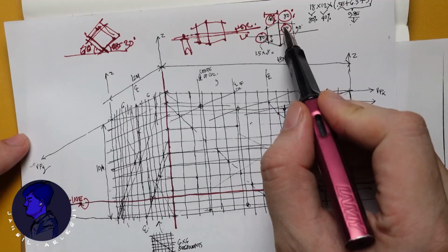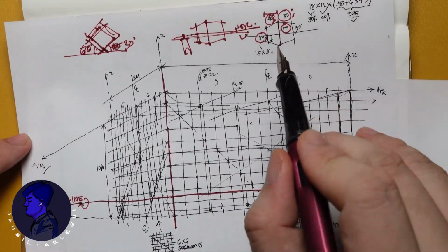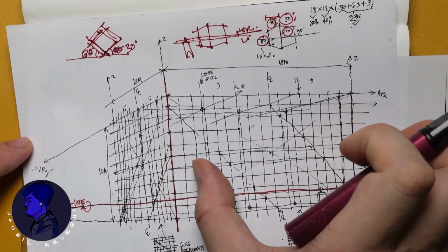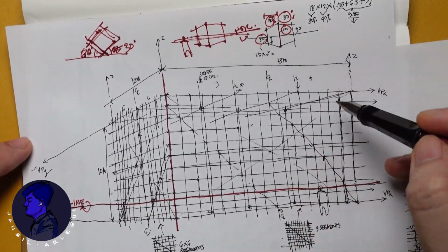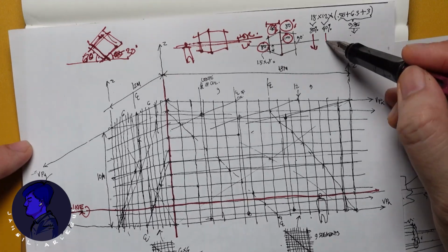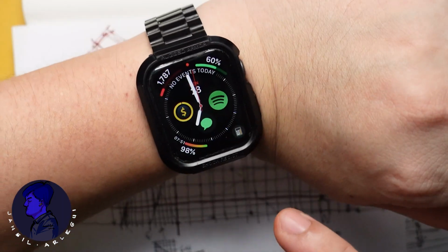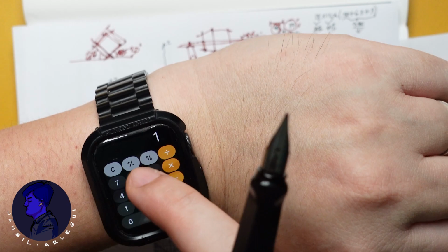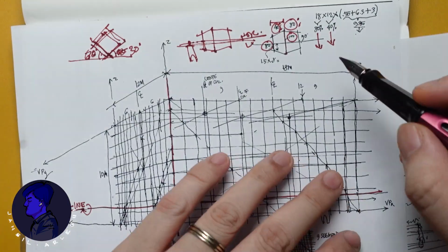When you're trying to plot a perspective with frameworks like this, the width is going to be 80%. So 80% for this rectangular framework, which is 18 meters. I measured 80% of 18, using the same scale to measure this. If you calculate that, 18 times 0.8 would be 14.4.